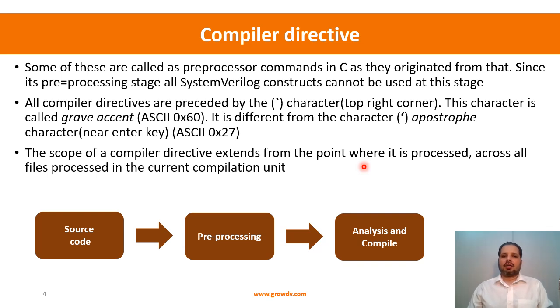Since we say it's a pre-processing stage, the SystemVerilog compiler has not kicked in yet. So what happens is you have source code, and then a step called pre-processing takes place, and only after the pre-processing step has completed does the actual analysis of the SystemVerilog constructs and the compile process for them start off. The compiler directives get processed in this particular stage. So at this stage, the awareness of the SystemVerilog constructs is not there.